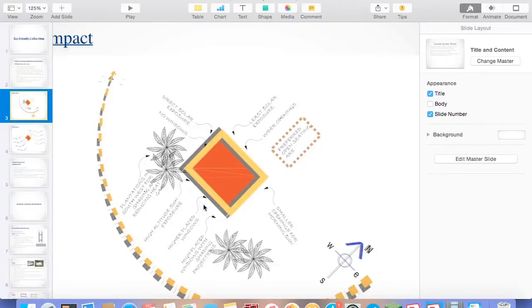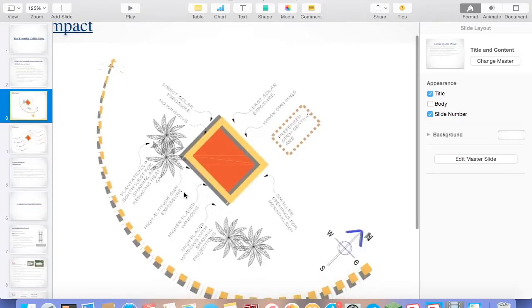And then here we have high altitude sun exposure, so we can have some windows here because it will be good for the air ventilation, but then we should have it protected enough with the horizontal projections so that we don't get the direct sun rays into our buildings.